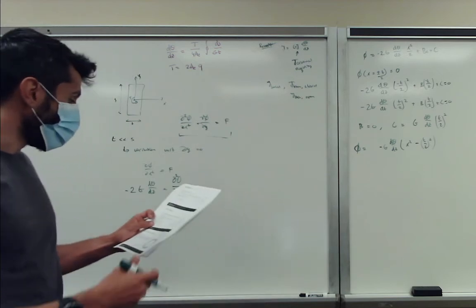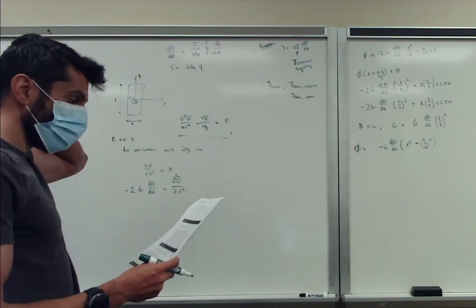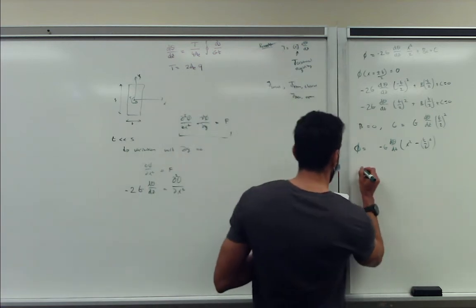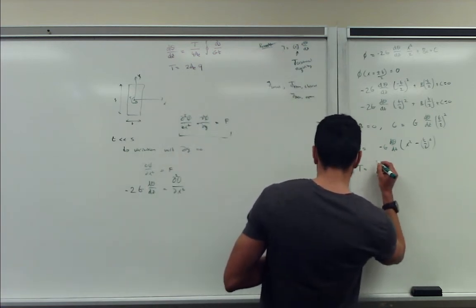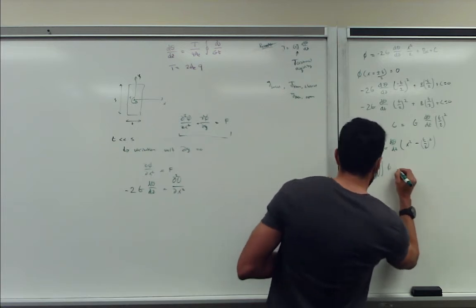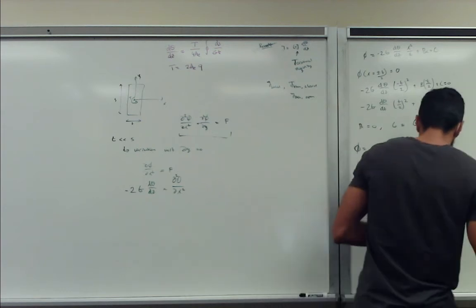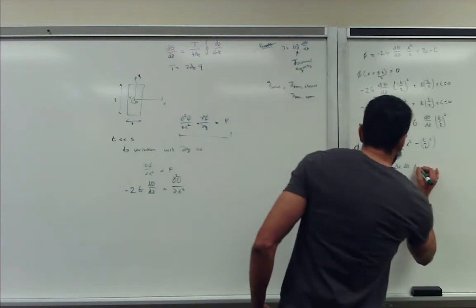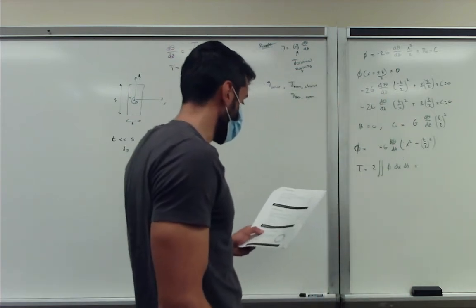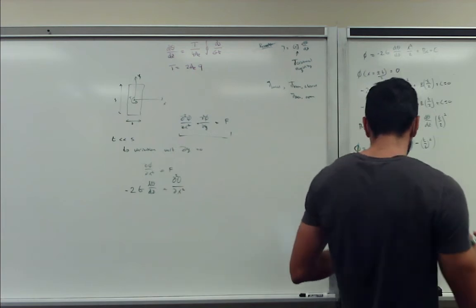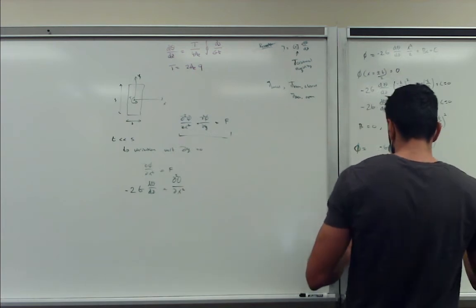And then next, in order to come up with the torsion rigidity, we know that our torsion must be equal to 2 times the integral of phi dx dy. If we write this out and take the integral, I'll skip the integral part, it's not that important, or not that interesting.